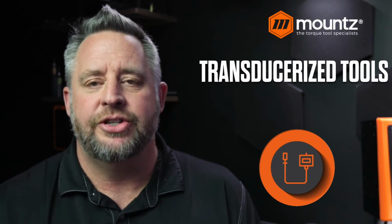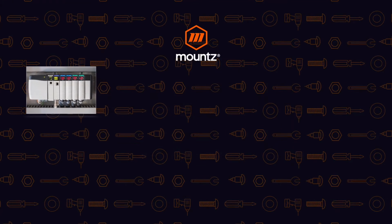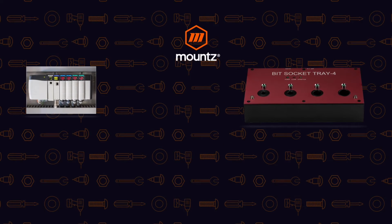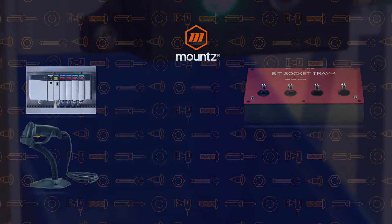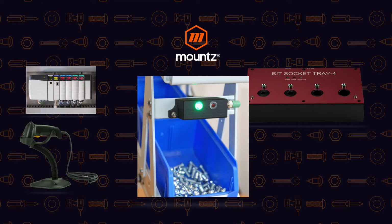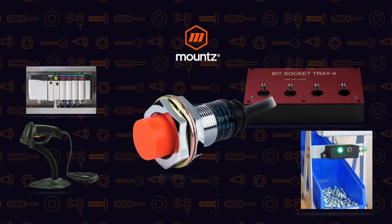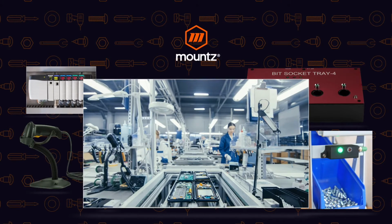And so that's going to bring us to what we're looking at with different smart control line devices. I mentioned the PLC, which can control a lot of what's happening. You have bit socket trays where the operator must pull the correct bit to be able to use. We can use barcode scanners to add data to that assembly or pull up a certain instruction. There are proximity sensors and pick-to-light sensors that can help guide the operator through the assembly process. And then we can also look at the use of part in and part out management as the part moves down the assembly.